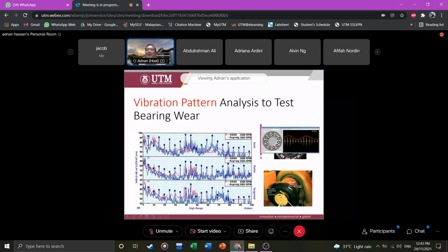Let's say this is bearing. You can monitor using sensors. You can monitor this vibration of bearing, put a sensor there, and the vibration from that parts of the devices can be collected, converted into electrical signal, and displayed in the display monitor. So you can interpret this, the behavior of the changes. Okay, when there is high peak, low peak, and also the cycle of changes. Okay, analyzing this pattern can give information to us when to change bearing. So again, it is pattern. Okay, it's a pattern.